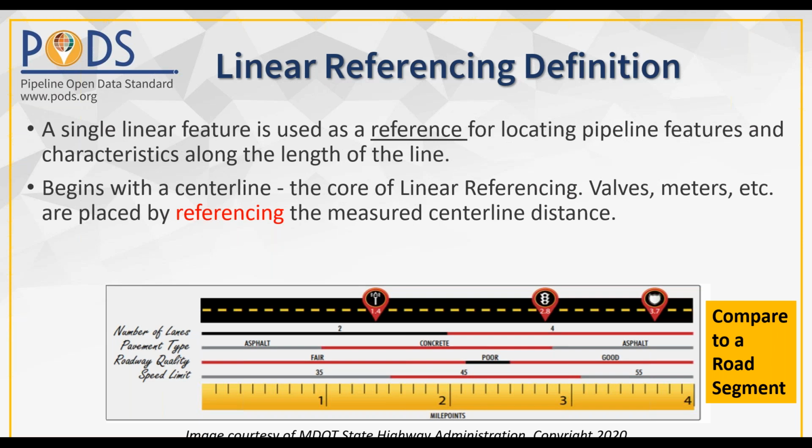In linear referencing, we can store all this without stacking up lines of polylines along this road network, because the linear referencing system is smart enough to calculate locations of each one of these attributes of the road without having to create new roads or new road segments themselves.